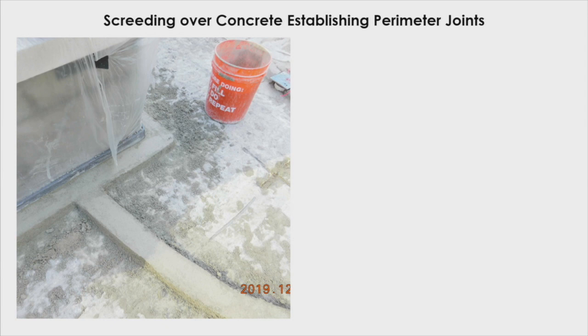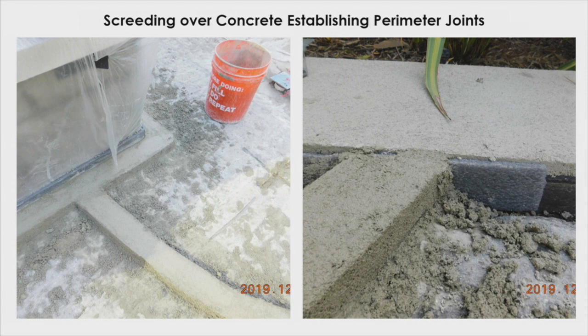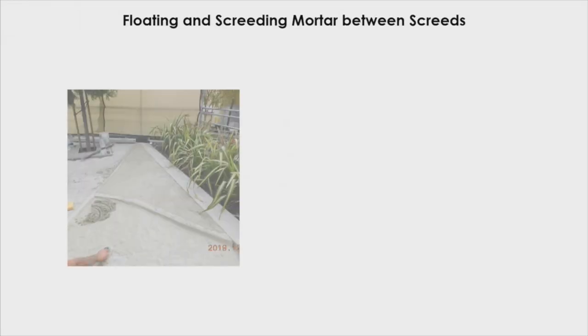Here, one of the things I wanted to point out, notice along the perimeter here, we have some foam. So we use concrete form foam. And we do that because all perimeters are supposed to have a movement joint. So this is an easy, fast way to establish a movement joint along perimeters. You use this foam and you can lay it out. And it's even perforated, so in some cases where once you get the tile up or whatever, you can rip off a section of it to get it at the level that you want it to be at.